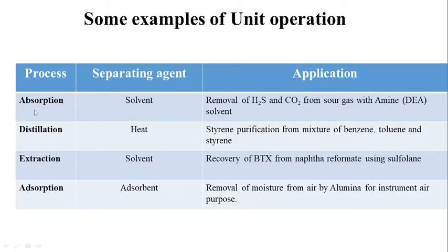These are some examples of unit operation. Let us say absorption is a unit operation in which we are adding solvent to the gas stream to absorb some of the component in the gas stream. An example of absorption is if we want to remove hydrogen sulfide and CO2 from hydrocarbon mixture, we can use diethanolamine as a solvent.